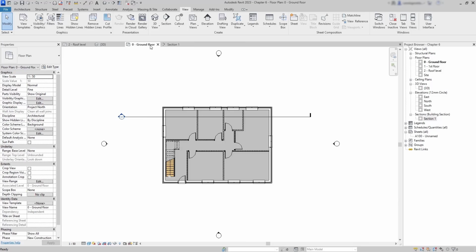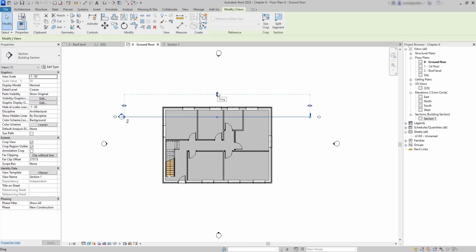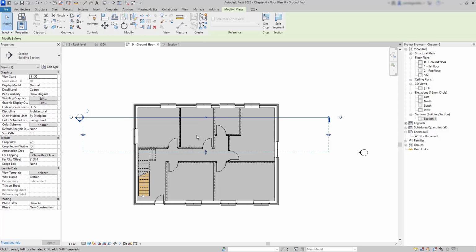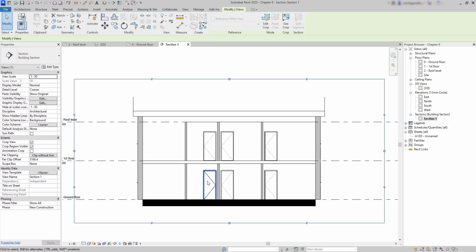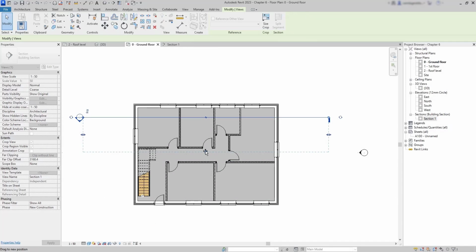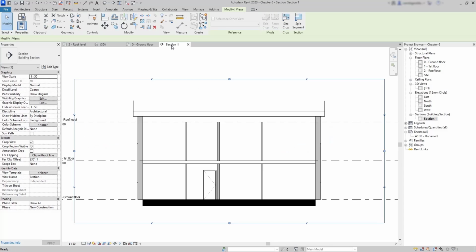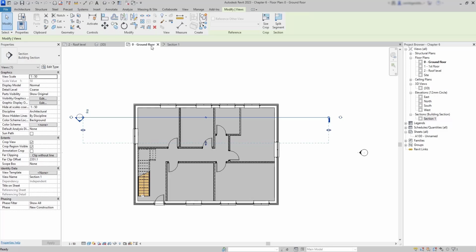Okay, we are going to learn how we can edit this. In this arrow, I can switch the direction of the point of view, and this time you can see it's facing towards the door. If I move the area in a way that I leave the doors outside, they will not show in the drawing, only the door that was inside. Finally, a similar situation is if I drag the area to the left, now this part will be hidden.